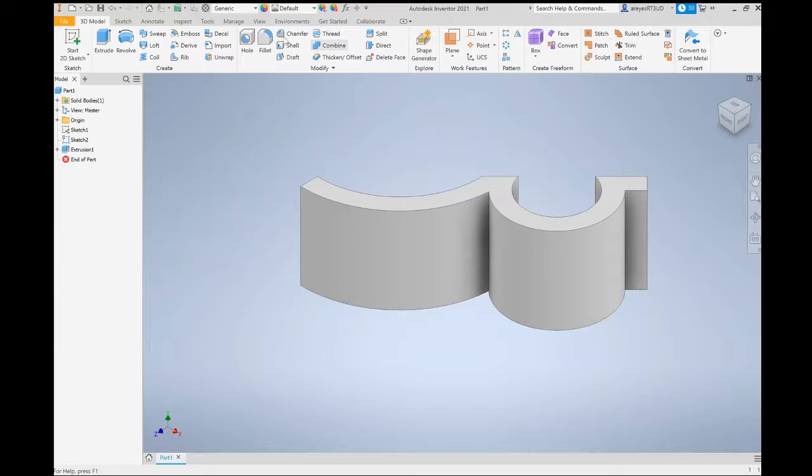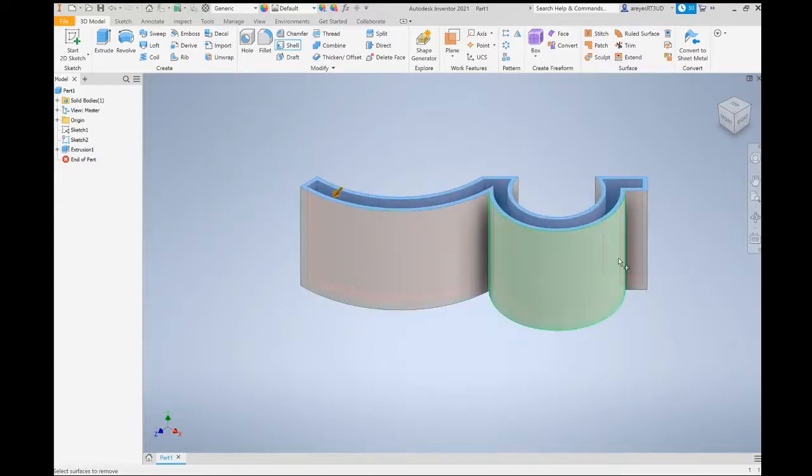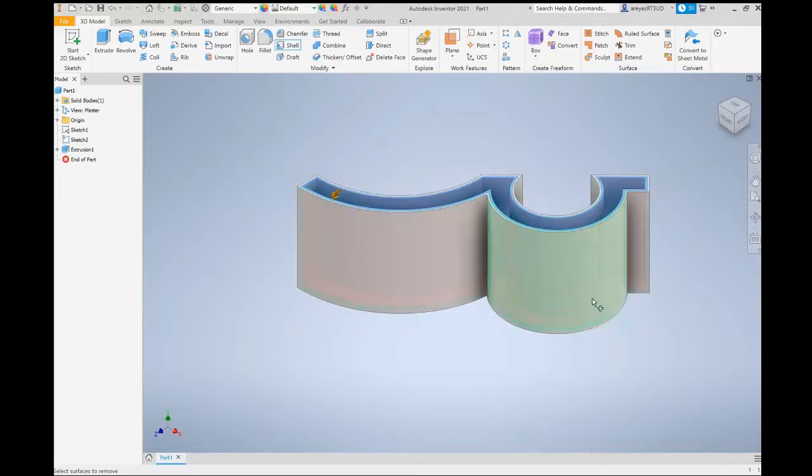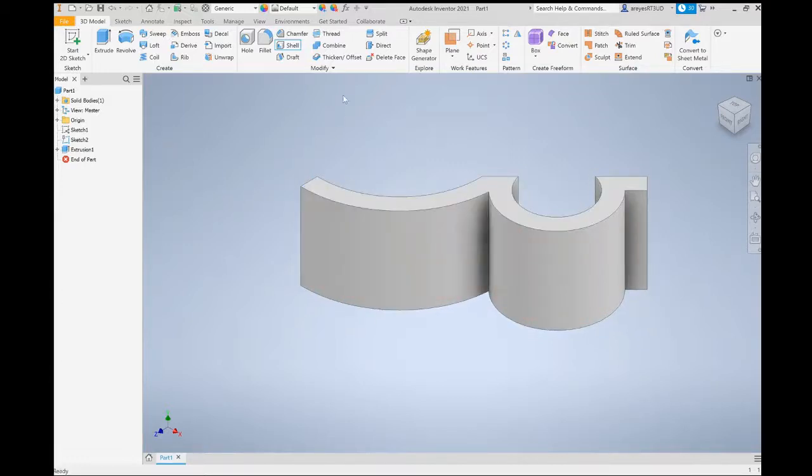And then for the shell, it's creating a shell-like feature, so you can actually change the thickness. So I'll change the thickness to 2 mm, point 0.2. So it's creating this shell structure, so you can see what would work. So this is inside, it's a shell outside, or in between. So please play around with that more. Okay, right. So I'll cancel that.